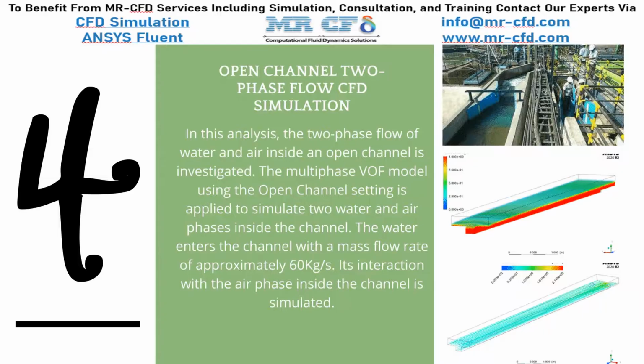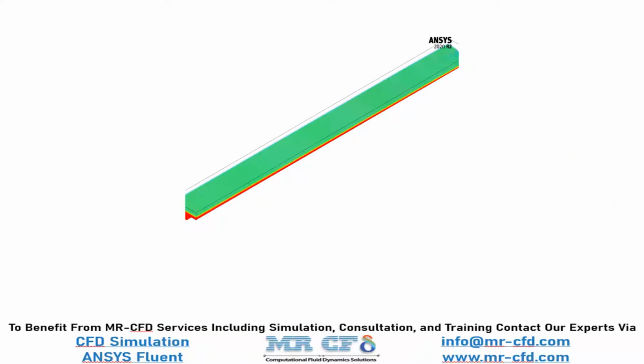In this project, we will simulate the air and water flow inside an open channel. The standard K-omega model is used for solving the turbulent flow equation. Also, the multiphase VOF model with the use of an open channel setting is activated to simulate two-phase flow of water and air inside the channel. The water enters the channel with a mass flow rate of approximately 60 kilograms per second, and its interaction with the air phase inside the channel is simulated.